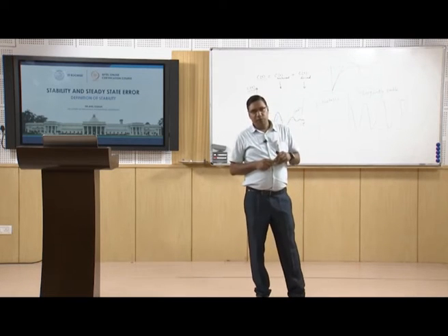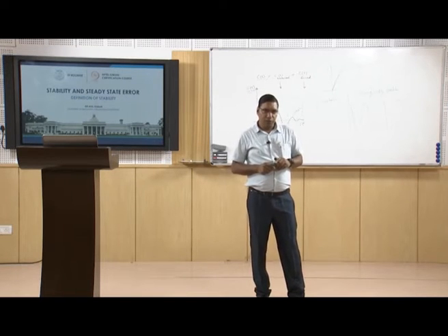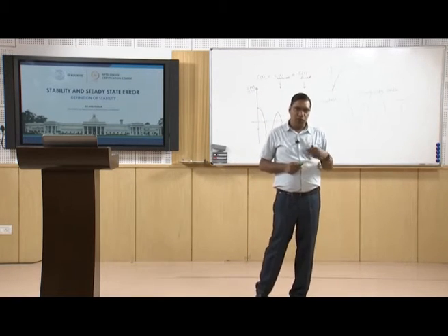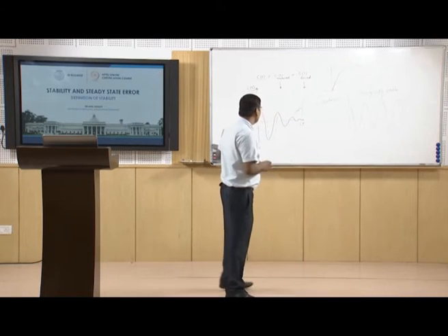The transient response we have already linked to the location of the poles. So we can also define stability with the location of the poles of the system.